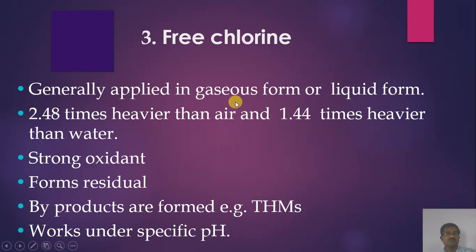Now next is free chlorine, generally applied in gaseous or liquid form, 2.48 times heavier than air and 1.44 times heavier than water. It is a strong oxidant. It forms residuals. Byproducts are formed, for example THMs, and it works under a specific pH.